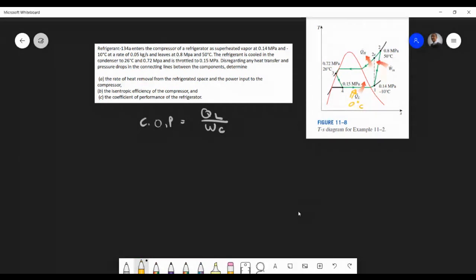Furthermore, on the condenser side, your condensing medium can't be more than your condensing temperature. Here we're sitting with 50 to 26, so this could have been around 30 degrees, because at 50 degrees it's giving heat off, rejecting it to the air, and hence the air will be cool up to 30. So your condensing temperature must always be higher, otherwise you're going to get heat in. The purpose is to have heat out, so this must be hotter and this must be colder. That's very important from a practical perspective.